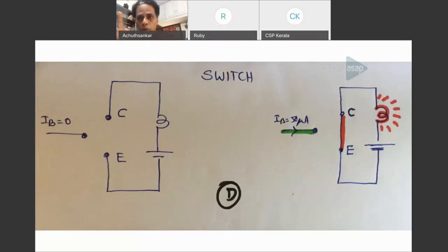So your output comes in the collector emitter circuit that is driven by the battery there. Actually, as we will soon see, the collector to emitter circuit produces a signal using its own power source, which has the same shape as the base signal.